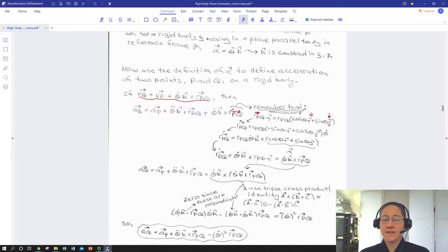So this is another way of defining our vector r_PQ in terms of that reference frame F. Okay, so we take the first time derivative of that. The length stays constant. We're not stretching anything. It's a rigid body. But then we take the first time derivative of cosine theta i and sine theta j, and then we get what's basically an expression we can relate back to U.